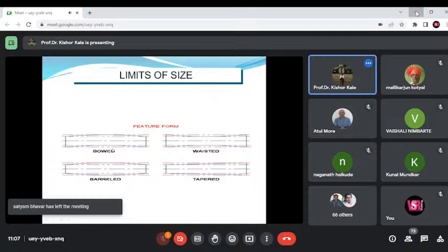So the same diameter is given. We can see the LMC in the blue one and the MMC in the red one. But by size, the actual shaft lies between the envelope of the given size, but the shape is bow shape, just like a bow. You can see this is being tilted like a bow. So the shape is like a bow. The black one shows the actual product, but by size it ensures that it is within the envelope.